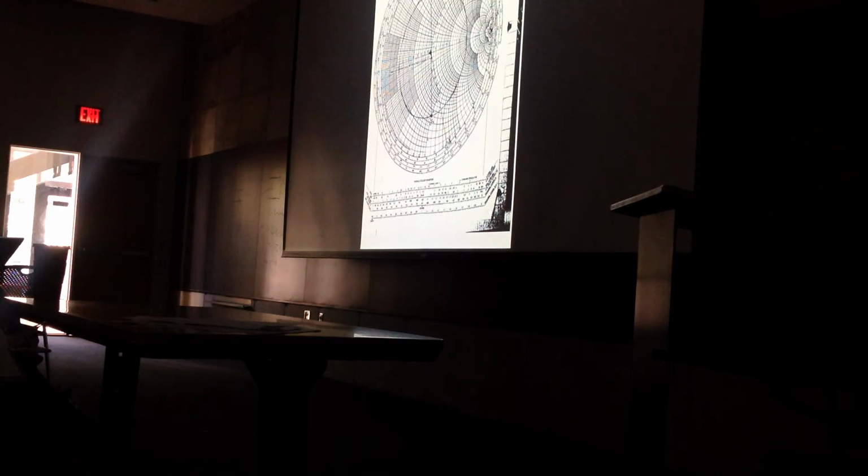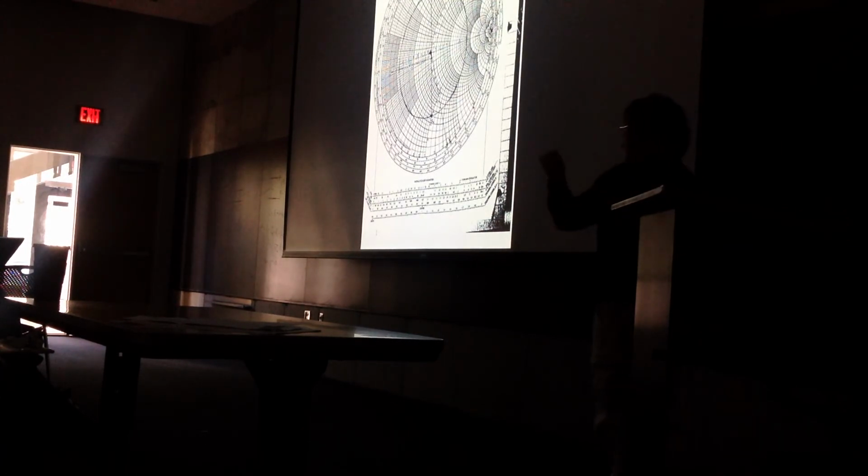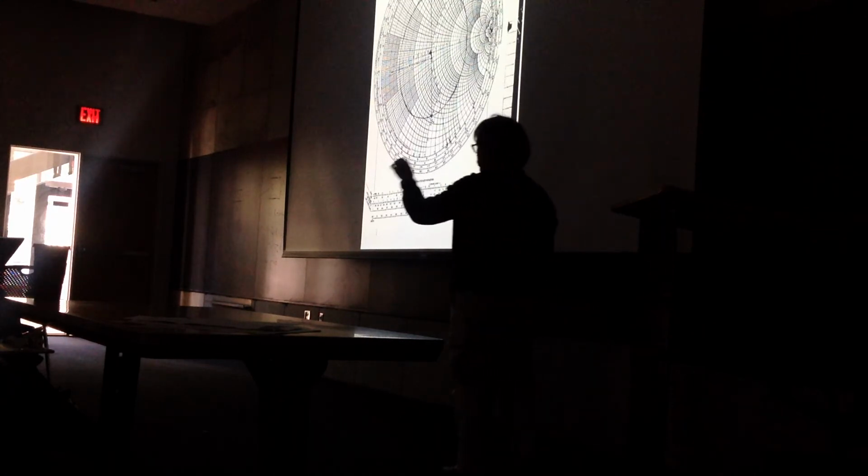And this is the distance that you need to travel. And here, if you look at here, it will be, say, 0 wavelengths, and then you go from this point to this point. It tells you how long that transmission line needs to be in order for a short circuit to become an inductor with the admittance of a minus j1.5.